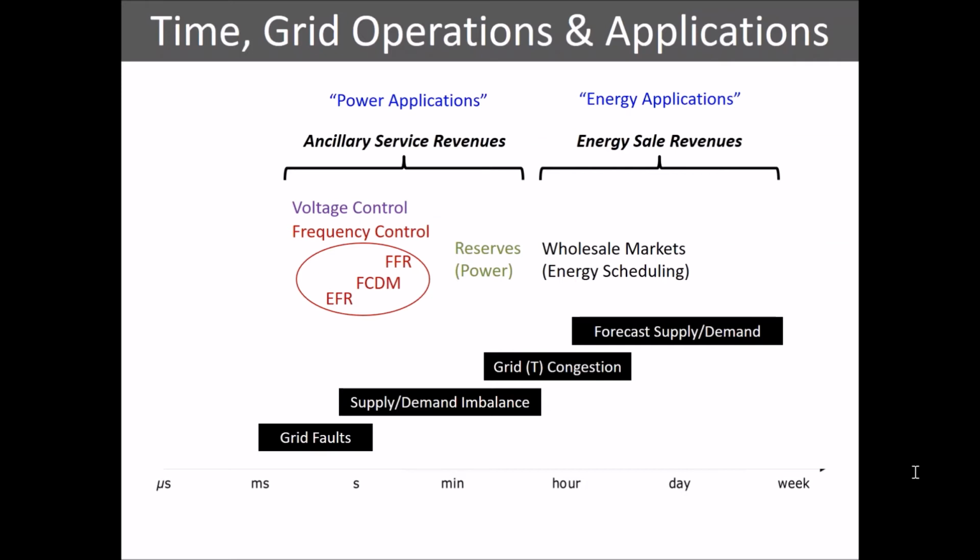So again, if a power plant suddenly drops off the grid, if we lose some supply, as well as immediately adjusting to make sure that the frequency is in balance, the short-term way of doing that might not be the most economic way of providing energy over a longer period, say 30 minutes, an hour. So we have other power plants, often in standby mode, which we can draw on as reserves, or power plants that can turn up their output as reserves over longer periods of time.